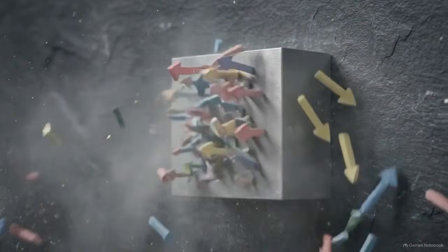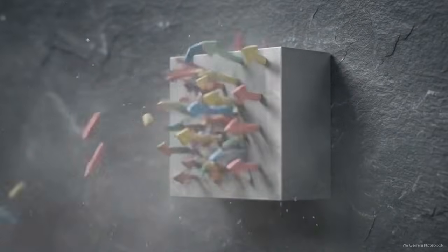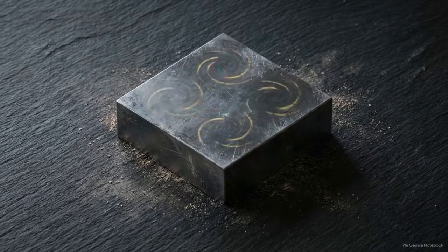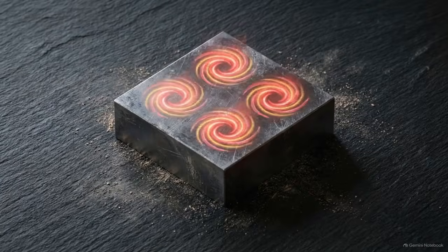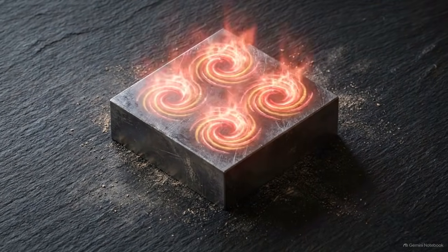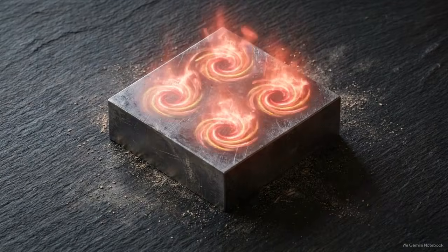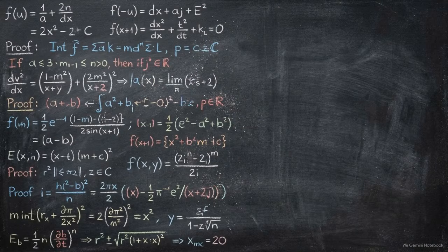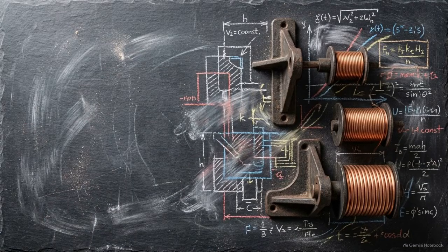This repeated switching creates internal friction that dissipates energy. Finally, the magnetic field induces eddy currents, small circular electrical paths inside the solid iron core itself, which steal power from the circuit. While the mathematical theory behind this is straightforward, the actual design of a transformer is a constant effort to mitigate these 4 thermodynamic drains.